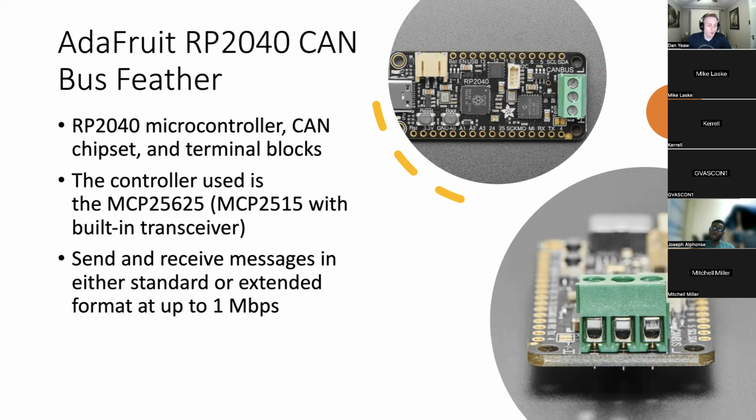And so I bought this board because I'm interested in playing around with CAN communication. And it's actually also used for other things, like race bicycles use CAN to communicate between the shifter and the shifting mechanism to make the shifts happen even faster. Robotics uses it too. So it is used for other things as well. So this is that, once again, this RP2040, and it has this onboard CAN that can send and receive signals. So my demonstration today is going to be on that, but you could easily use the Raspberry Pi Pico, which would work just as well, or many other CircuitPython boards.